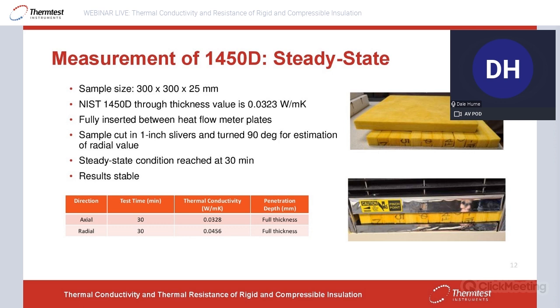And then we took, from a suggestion from a colleague, we were kind of curious of how we would approach an in-plane value. Now, this is an estimation approach only because there is an effect of putting materials like this together. There will be a parallel effect of that, but it's an interesting estimation of that in-plane value. We cut 1-inch slivers and turned them 90 degrees and sandwiched them, and put them back in. You can see that there is a very real effect of anisotropy.